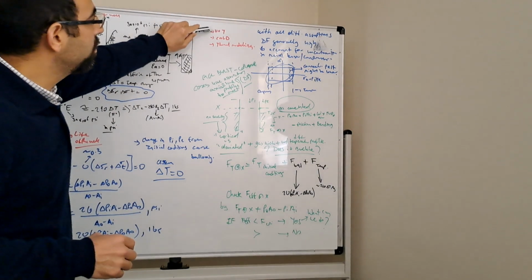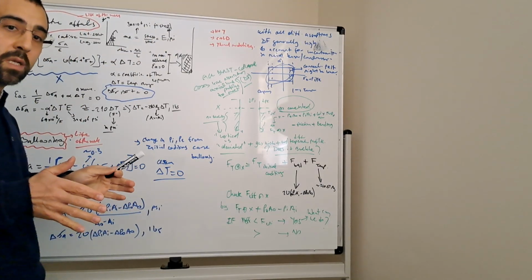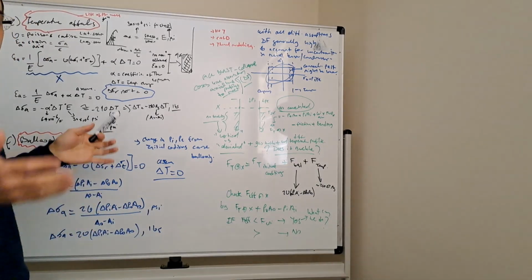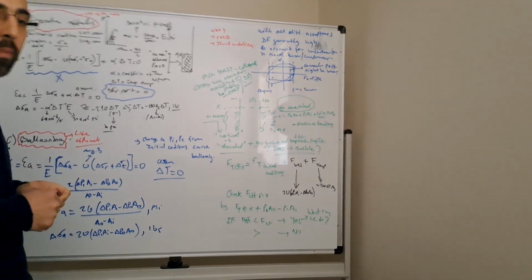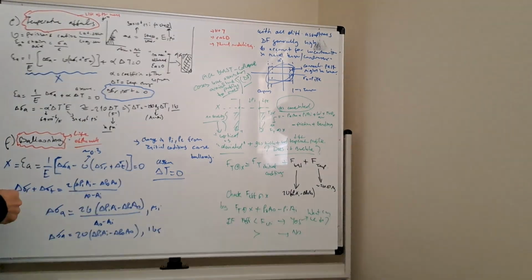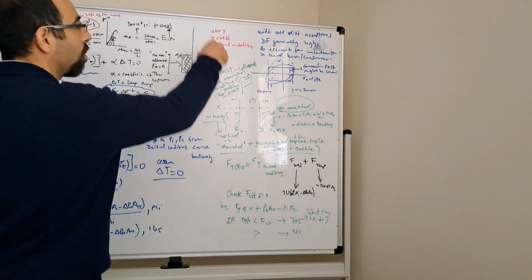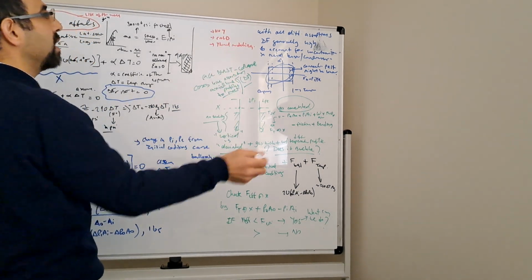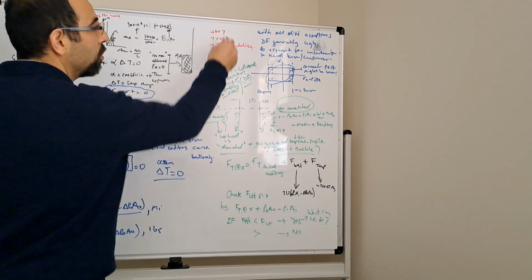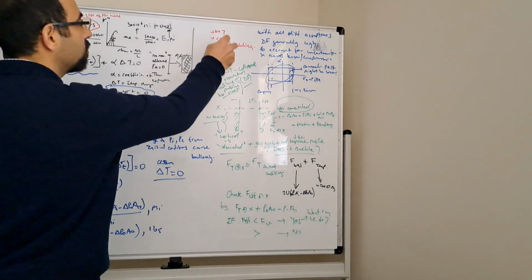for example, if the load case is hot or cold, because on the initial condition you have an associated temperature profile. It can be undisturbed or a geothermal gradient, or you can define it. However, in a load case where you have hot fluid pumping or cold fluid pumping, you get a kick. The formation fluid is coming in, so it will become hotter, or you maybe bullhead the well with cold water.